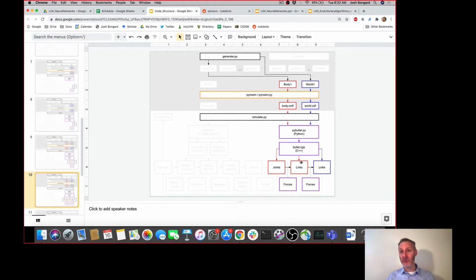How do they restrict the relative motion or orientation of links? Joints do so in Bullet by applying forces to keep the objects from, in the case of revolute joints or rotational joints, it uses a force to keep them from moving apart. So if other forces are acting on those links that are trying to pull or push them apart, the joint will apply forces to keep them having the same relative position, but they are free to change their orientation. So all the movement you see in a simulation is being caused by Bullet, which is applying various forces to